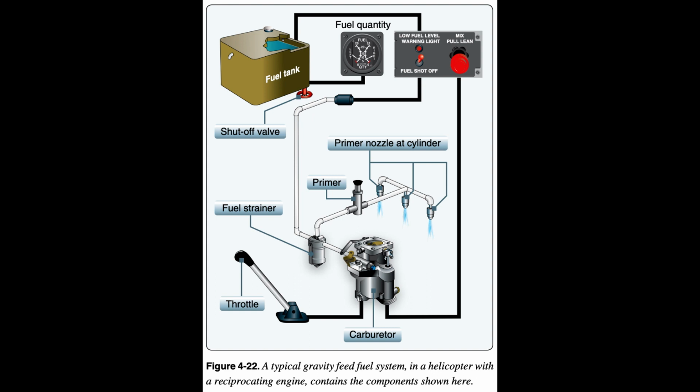Additionally, 14 CFR Section 27.1305(L)(1) requires newer helicopters to have warning systems provide a warning to the flight crew when approximately 10 minutes of usable fuel remains in the tank.